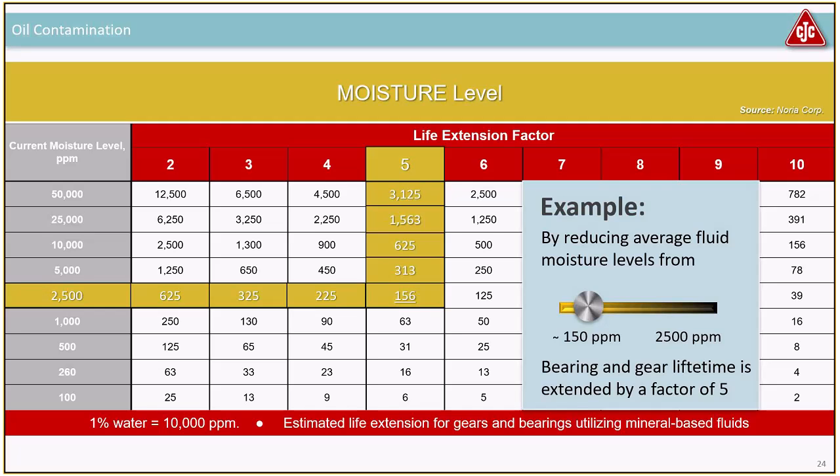If you had another application where you had a lot of dirt coming in, like a cement mill or a crusher or something else where there was a lot of dirt, I would focus on the particles and disregard the water, and then say, okay, you get 4 or 5 times longer life due to the particles. So that's typically how I would do it. Because when you look at adding them and you have 8, 9, 10 times longer life just by cleaning the oil, it gets a little too weird, a little too theoretical. So therefore I would normally pick one of them, and still the business case is fantastic. That's what I would normally recommend.